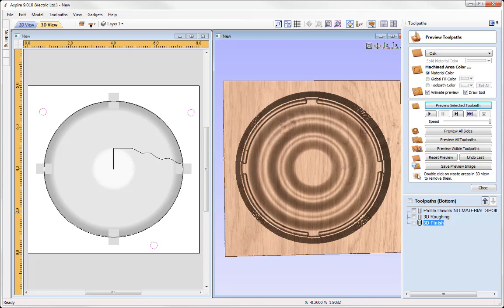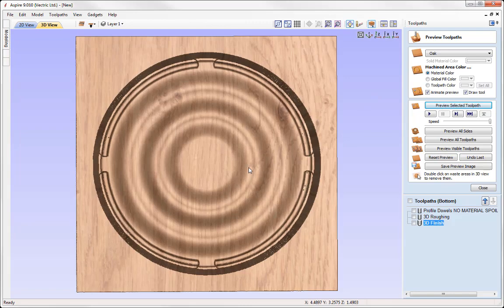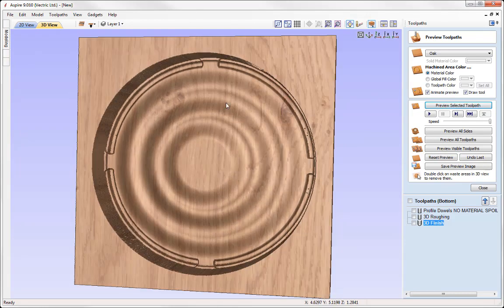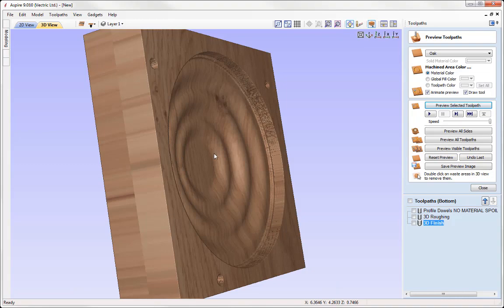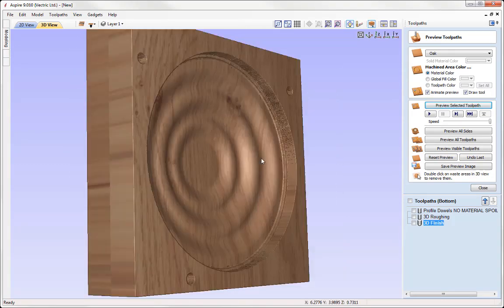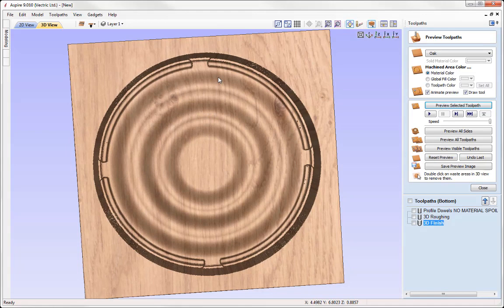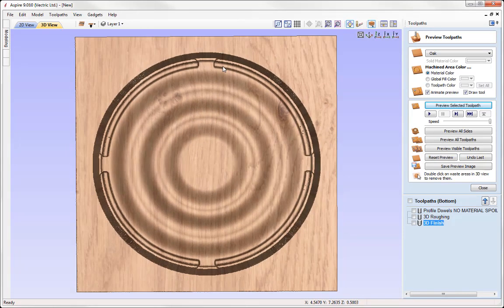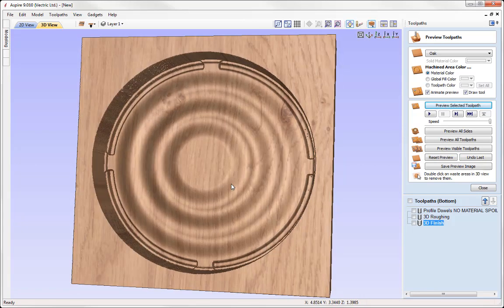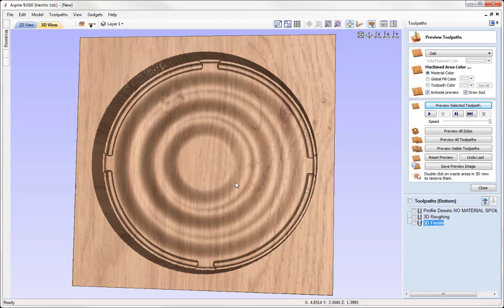and see how the part would actually look when we come to cut that out on our CNC. So if we maximise the 3D view and take a look at the part, we can see that it hasn't actually cut all the way through the two sides, and that goes down to the fact that we are using a rounded tool to finish the part, so we will be left with cusping as only the centre of the tool would ever reach the bottom there. And if I just hold down control, you can see that we have a very teeny tiny thickness there. So we're just going to look at introducing a negative plane just to drop that tool so it cuts through and will ultimately remove that cusping effect.